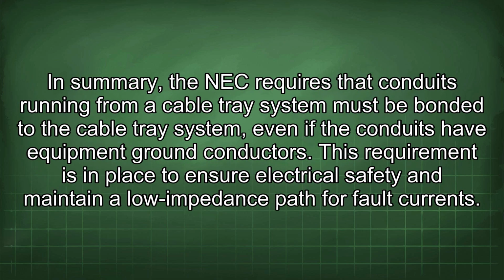In summary, the NEC requires that conduits running from a cable tray system must be bonded to the cable tray system, even if the conduits have equipment ground conductors.